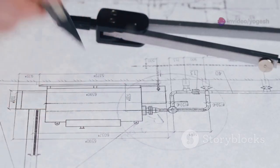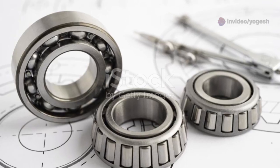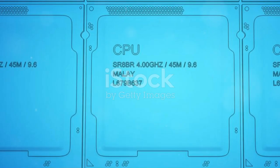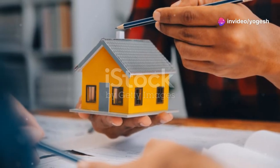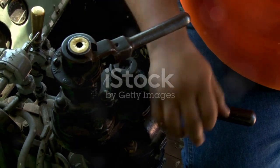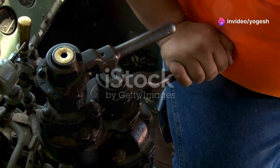manufacturing and inspection. Each type of sectional view, full, half, offset, and aligned, serves a specific purpose, helping you choose the best way to communicate your design intent. Selecting the right sectional view is key to making your drawings clear, concise, and easy to understand for everyone involved in the project. Remember, sectional views are all about making complex parts understandable. Use them wisely to ensure your designs are interpreted correctly and efficiently.